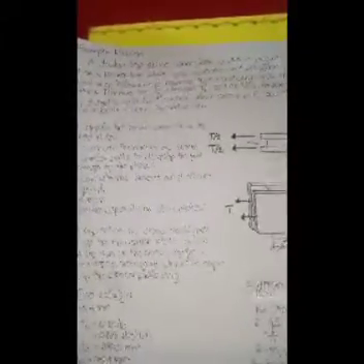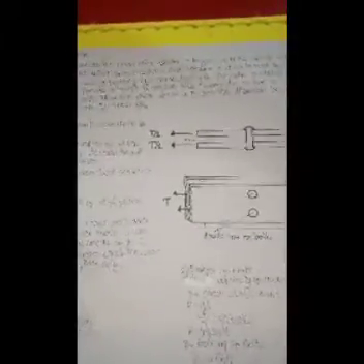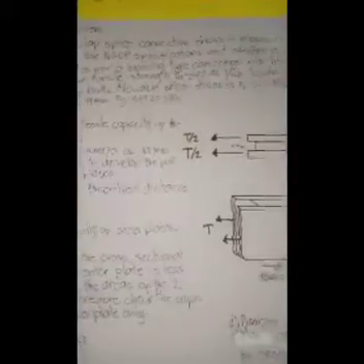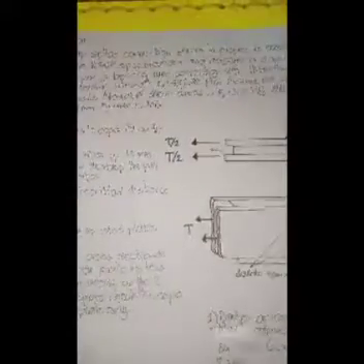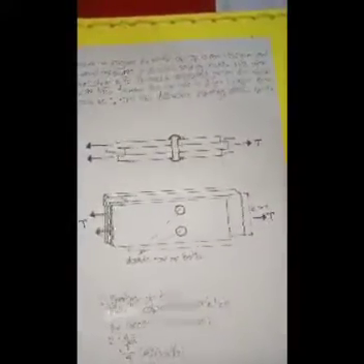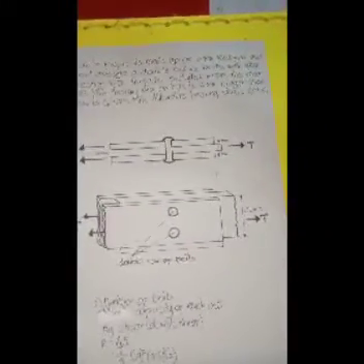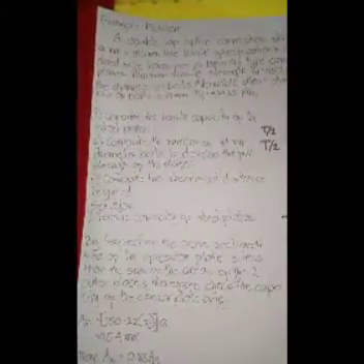Minimum tensile strength F sub U is equal to 552.93 MPa. Assume diameter of hole is 3 mm bigger than the diameter of bolts. Allowable shear stress is F sub V is equal to 207 MPa. Allowable bearing stress is F sub P is equal to 1.2 F sub U. Diameter of bolts is 19 mm and F sub Y is equal to 449.25 MPa. Then the 3 questions.